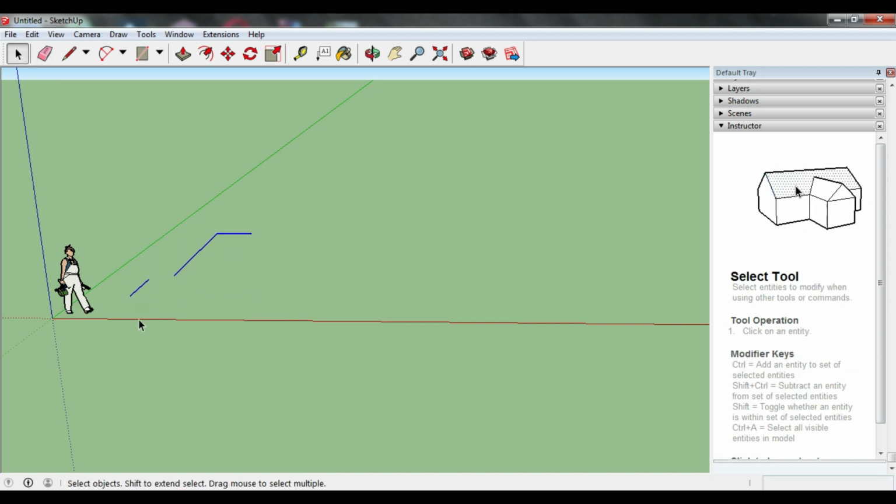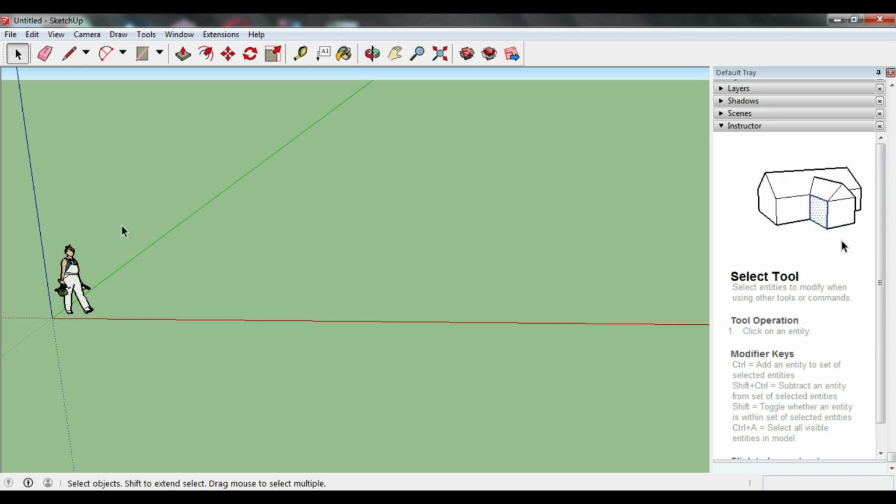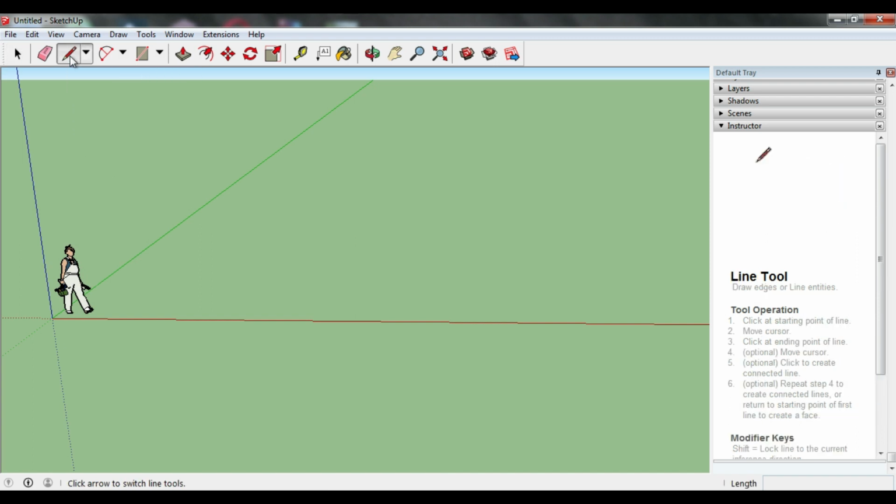Let's talk about drawing. Drawing in SketchUp is fairly simple. You can either activate a tool or type a keyboard shortcut. Let's try drawing a line again. To draw a line, it is important not to click and drag. Just click and move in the direction you want to draw and type a length for precision. Again, just a single mouse click. Type value and click or press enter. A trick to make sure that you draw along the axes is that when you activate a tool, tap the arrow keys. This will lock your tools to different axes.